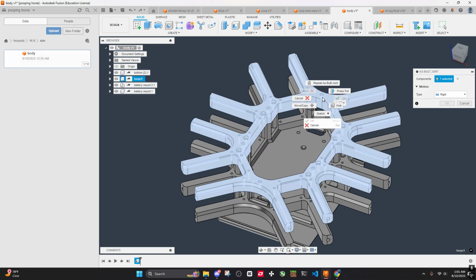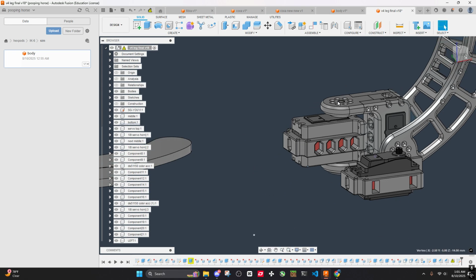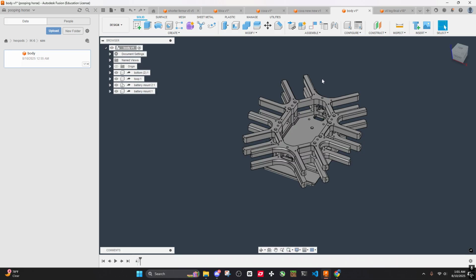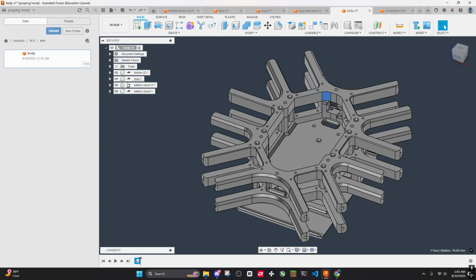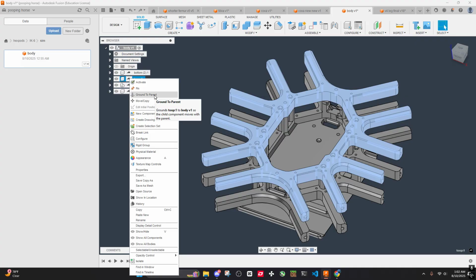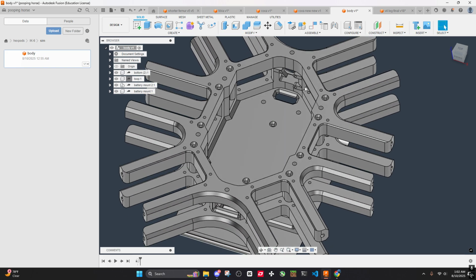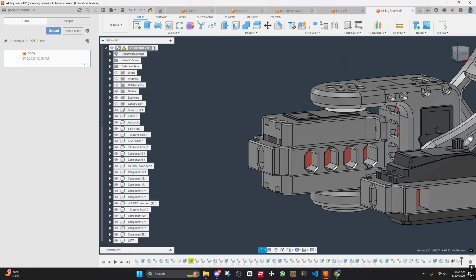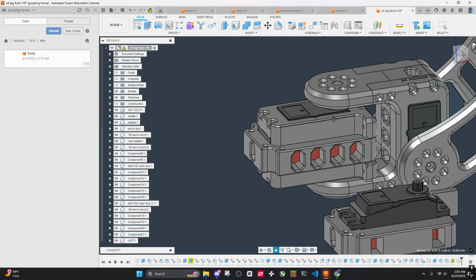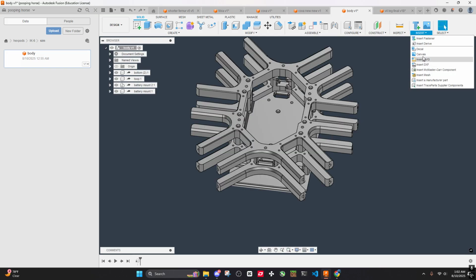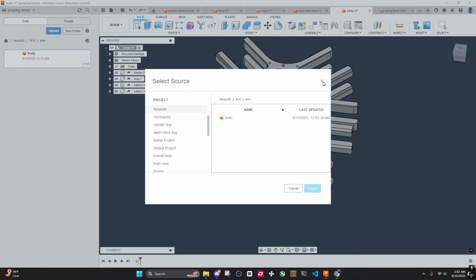There's a way to anchor it which says that this is a foundational part, nothing should move. When you assemble other components relative to that, it tells the ground system that this thing is the parent. So you can ground all these parts in the center, and this whole block you ground together as one, then you can import that as an instance in this part, and it stays as a single unit, and you can move it because it's an instance.